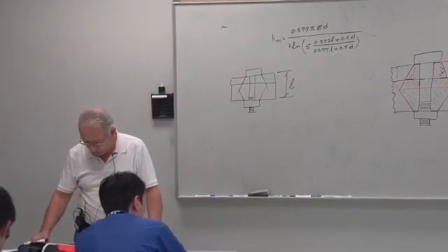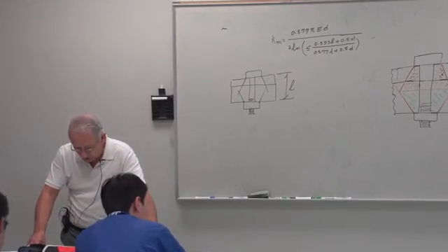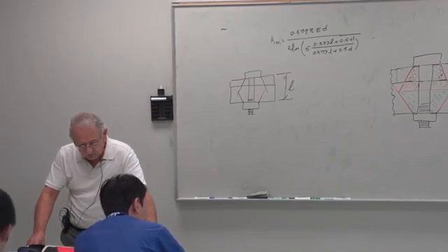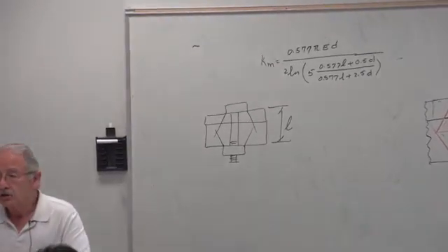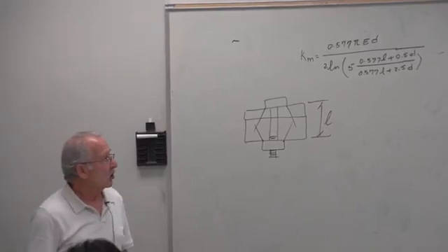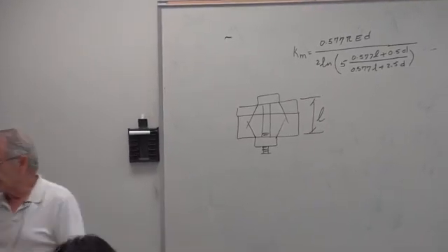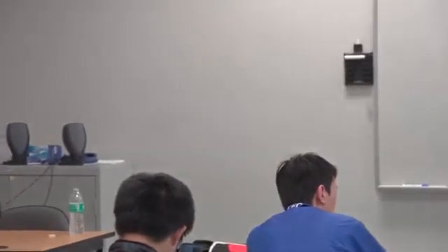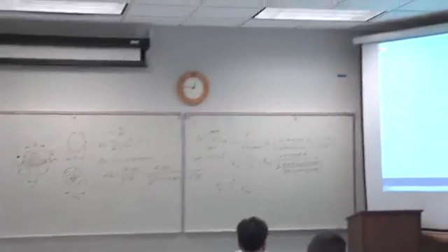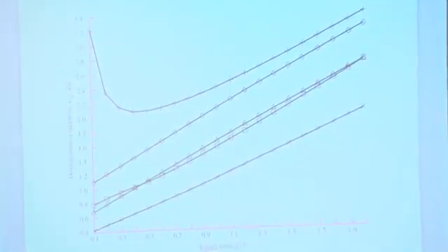There is also an experimental procedure to give you this very same Km if the materials of the members are the same. And that's shown. These are various experiments with this Km. What you get on the side is Km over ED on the vertical axis, and on the horizontal axis, the aspect ratio, or D over L, diameter of the bolt divided by the grip length.